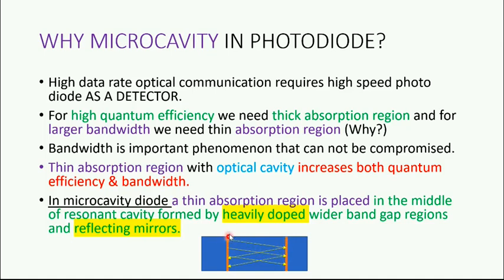What will happen then? When some rays manage to reach the depletion region where immobile carriers are present, these rays undergo multiple reflections. I am showing only 3 rays here. They come here, go back, come again, go there, so multiple reflections are there. Because of multiple reflections, more carriers are generated, because these rays are absorbed by the immobile carriers, making electron hole pairs, right?